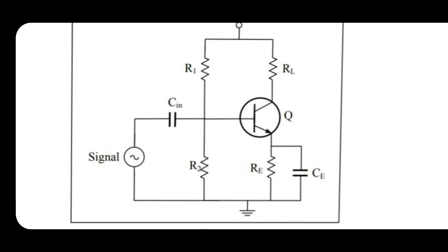The result is an amplified AC voltage across RC and RL. The amplified collector current flows for 360 degrees of the input signal. For a full input signal, a full output cycle is obtained. Here the signal is a faithful reproduction at the output without any distortion. This is an important feature of Class A operation. However, the efficiency of Class A operation is very small.